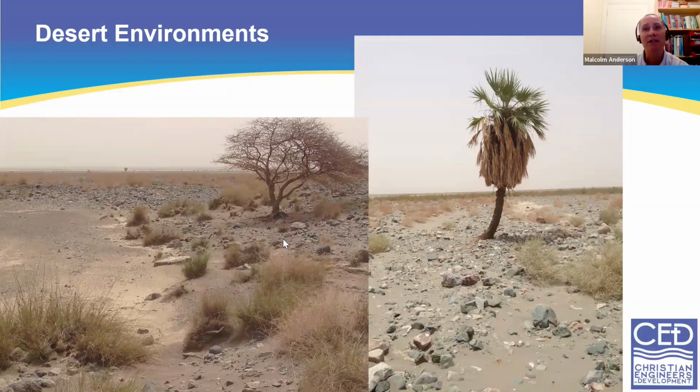And then on the left here, this is the classic acacia tree. Acacia trees have root systems that can go up to 20 meters deep. It's the complete opposite. It's actually in virtually the same location as this palm tree. The palm tree is down in the horizon, and here the groundwater level is quite a lot deeper. But this acacia is surviving because it's able to capture moisture from 20 meters down, and so it has a completely different system of survival. So just those two different trees tell me how deep the groundwater system is.